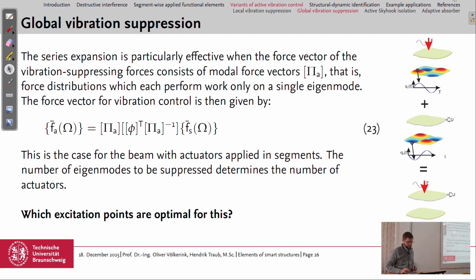So the force distribution that performs work on only one specific eigenmode would be a modal force vector, and it would not perform any work on the other eigenmodes.